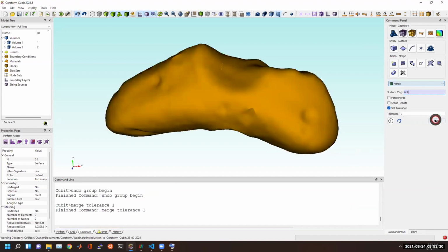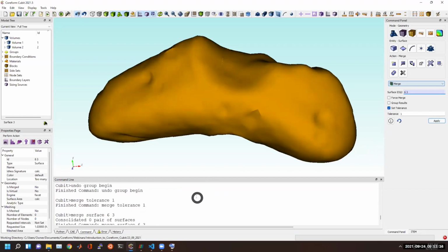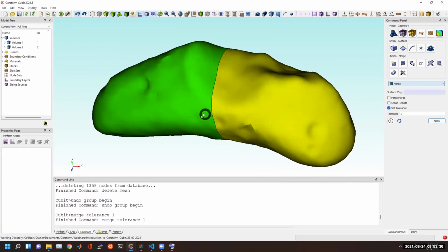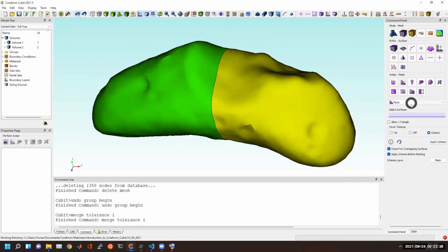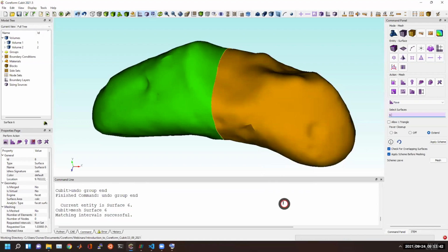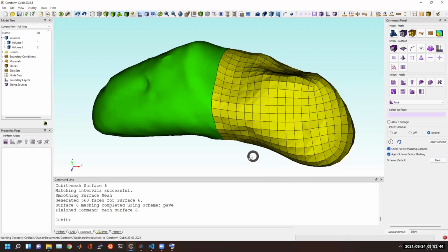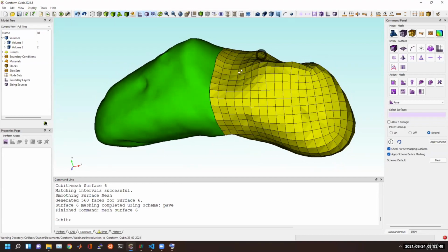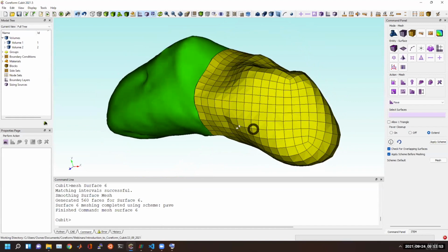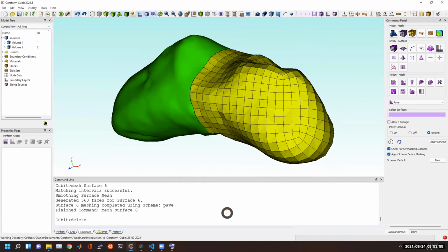So this is how we do quad remeshing in Cubit, is just to use our built-in paver on the surfaces that you have. So is that helpful guidance? It's fitting, then these quads are then being projected to the input triangulation that we had. And so we could even set this to be an even finer mesh.